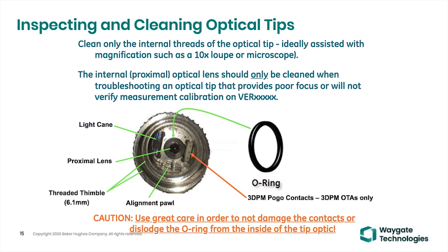Yeah, Tom, that's a great question, because there are inspection requirements where the camera is absolutely going to be exposed to liquids, whether it's oil or otherwise. And so my first thought is that something about the insertion tube is not watertight. It's easy to tell if there's damage by just taking a thin shop towel, lightly moistened with, I start with water, I use alcohol as a last resort if it's not coming clean.